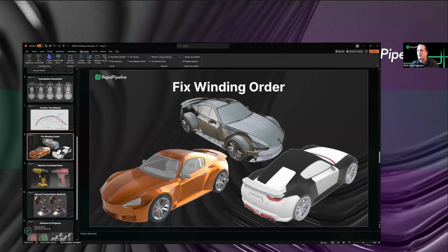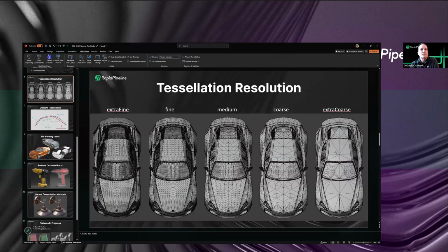So let's take a look at your Q&A and see. I think we have 4 questions here. The first question I see there is, how do I get smooth meshes when the CAD is really chunky? Yeah, so that really depends upon the resolution that you tessellate at.